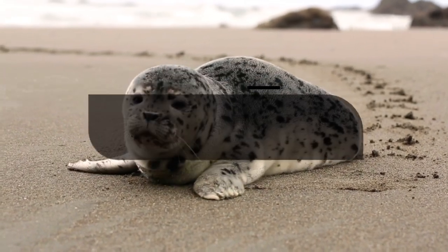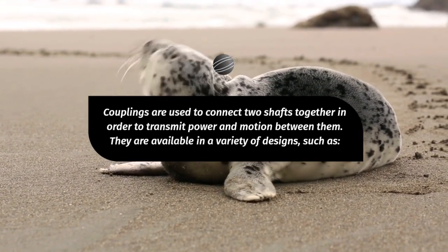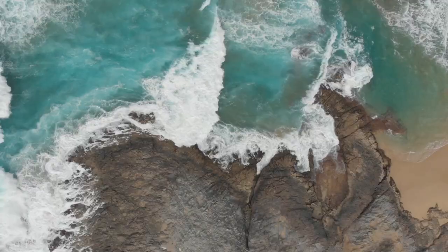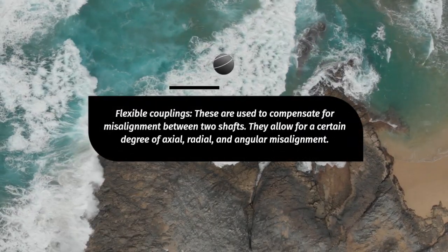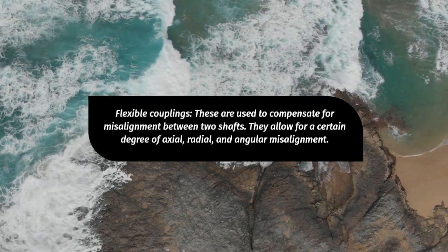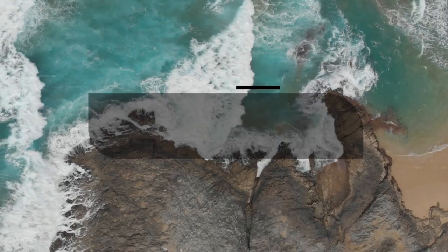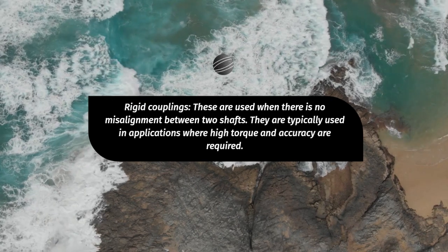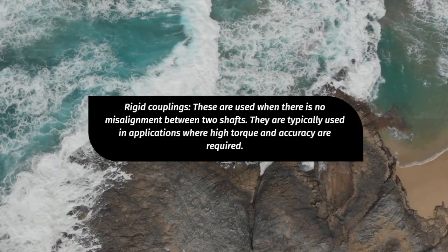Couplings are used to connect two shafts together in order to transmit power and motion between them. They are available in a variety of designs, such as flexible couplings. These are used to compensate for misalignment between two shafts. They allow for a certain degree of axial, radial, and angular misalignment. Rigid couplings are used when there is no misalignment between two shafts. They are typically used in applications where high torque and accuracy are required.